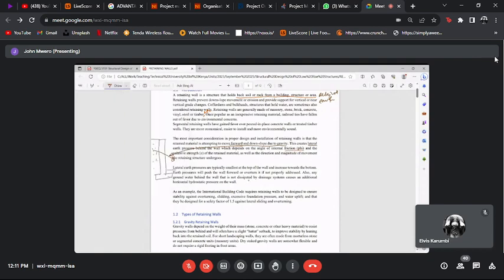But you'll remember from your soil mechanics the angle of internal friction, phi, and the cohesion of the soil. We will look at this in some detail slightly later in this discussion, and how they affect the push that the retained material is pushing the retaining wall with.